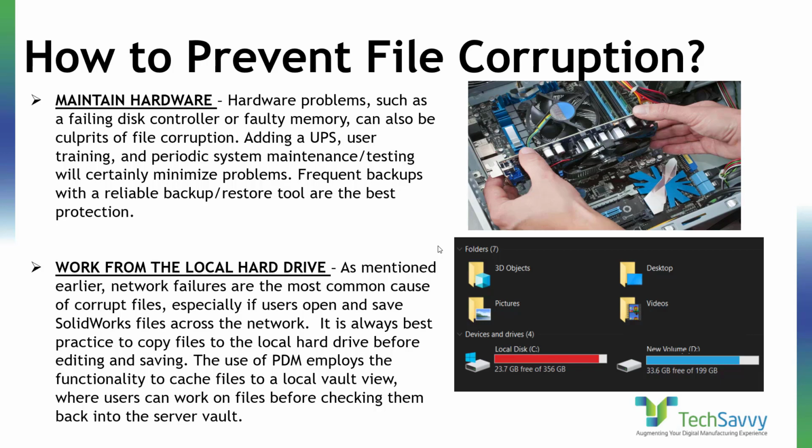As mentioned earlier, network failures are the most common cause of file corruption, especially if users open and save SolidWorks files across the network. It is always best practice to copy the file from the network to your local hard drive, then work, and then save it back to your network.